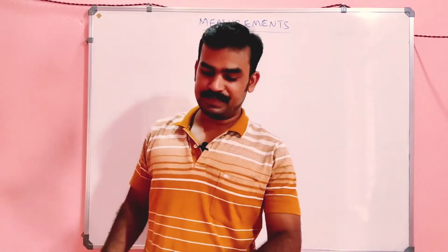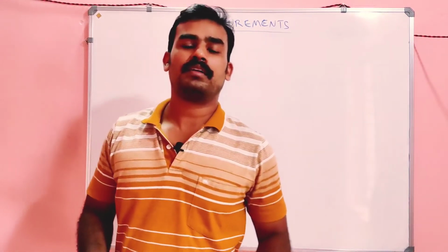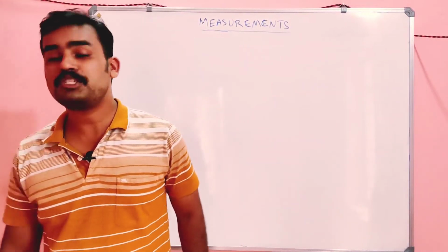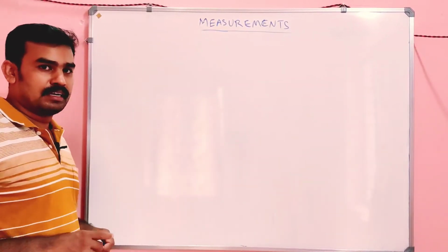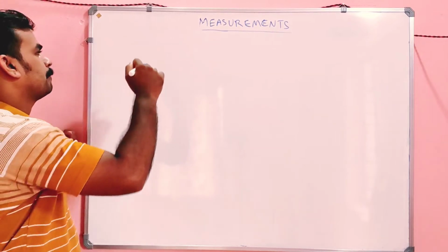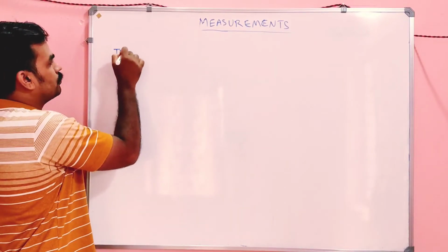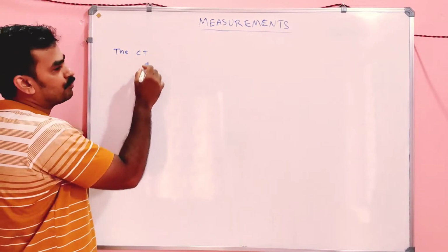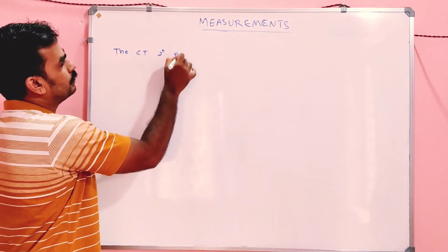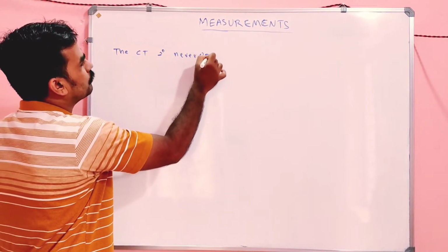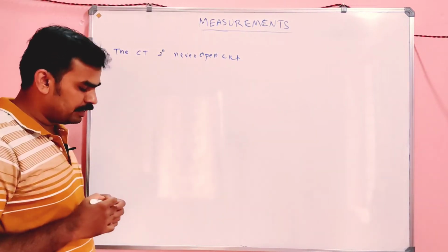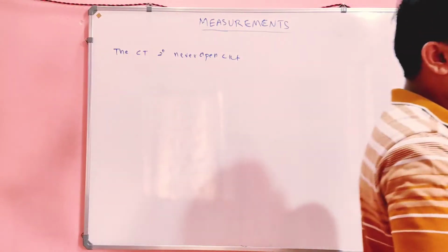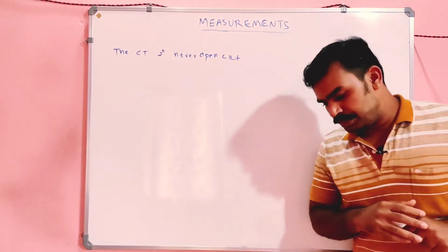We studied about the instrument transformer, right? And I want to add one important question regarding the instrument transformer. That means the current transformer: its secondary terminal never open circuit. Never open circuit. This is very important regarding the current transformer, because I already discussed it to you.